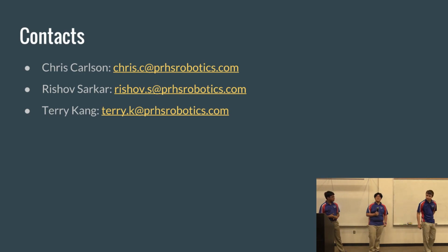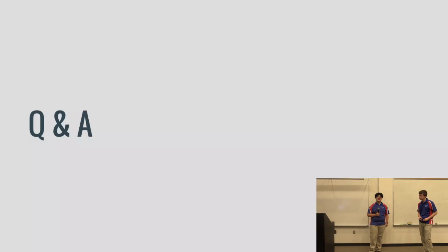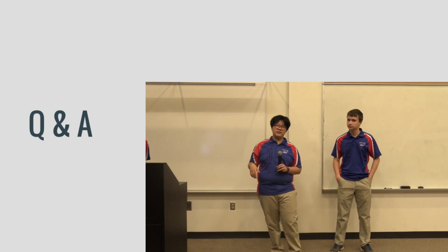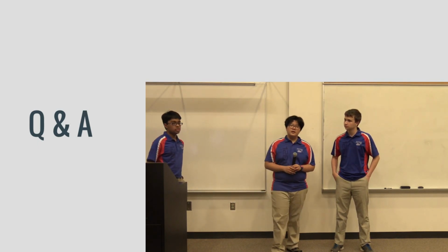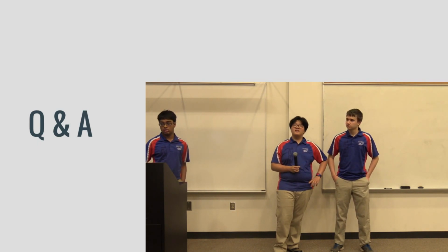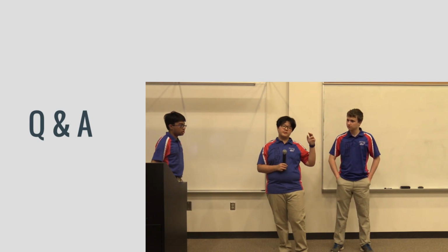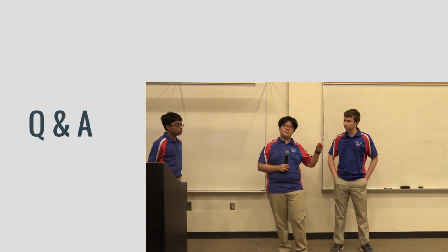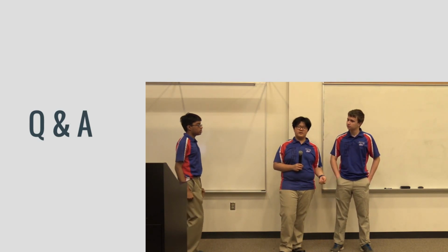Okay, so you're testing my memory because I don't remember things very well. Because Raspberry Pi is a Linux machine, there are certain things that Linux allows you to do through drivers, such as setting exposure values. Yeah, V4L, Video for Linux. If you go online, try Googling, there's a specific command line prompt that you can enter into the terminal to set the exposure value for a particular webcam.